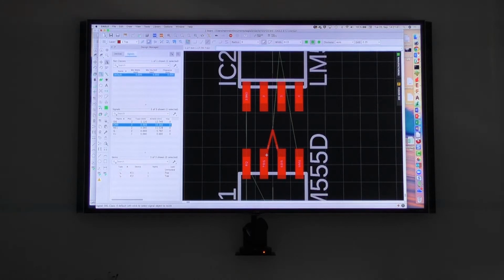If you have problems with space, you have 150 micrometers between the SMD pads. Every micrometer counts, and something like this is a problem. So you should align your components, not the components, the SMD pads or the pads, on the grid, so that I can really go out of the center of the SMD pads, so that I can keep my distances to the SMD pads next to this one.